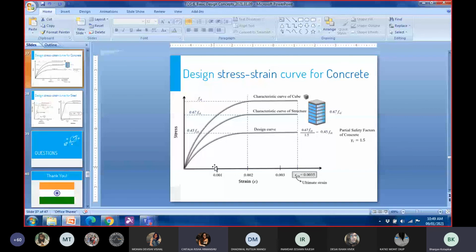So when you said when the pressure applied is 40 megapascal, how does it fail at 32? The cylinder fails at 32, not the concrete cube. And that is because of the size. Of course, there are other effects also, which I don't want to get into. There's the platen effect, and the cylinder is slender as compared to the cube. A lot of other effects, but the fundamental is that the size is different. And therefore the failure value is different. In short,